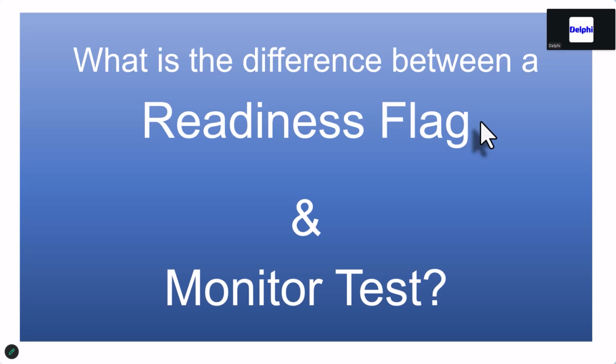So whatever they were doing was right, they weren't finishing off. So the readiness flag would stay incomplete. The monitor tests were not all done. So when they're all done, then the readiness flag can flip to complete and sign it off. Prior to OBDII, complete could mean it was done, it passed, and incomplete meant it didn't finish, or it could have been that it failed. So we have to be careful of this terminology.